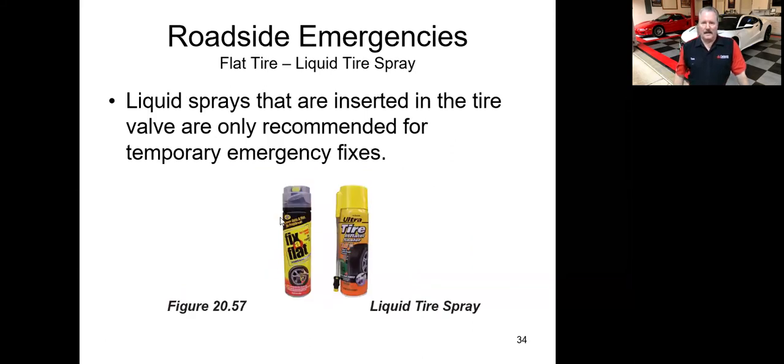This is something a little controversial, but you know what? If you had one of these cans in your trunk and you're out in the woods and you ended up with a flat tire from a nail or something, I would definitely want to put these in my tire so I can at least get the tire inflated and get it to a tire shop to get my tire repaired. These do have some fumes inside of here that can cause an explosion at a tire shop if there's any spark around the tire, if they're filled with this stuff.